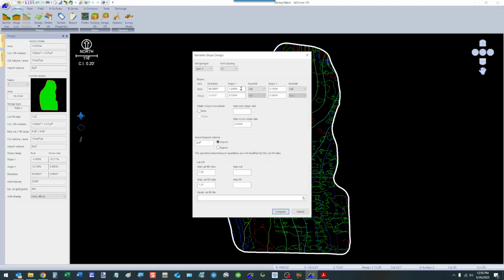So in this case, it'll fall no more than 1 foot fall per 100 feet. It will fall at least 1/10 down the middle, and it can go up to 5/10 fall side to side, north or south. So we don't care because we're going to have a row that is going to contain the water. And in my experience, in doing this for years, whatever this slope is right here, I try to keep it somewhere between 3 to 5 times whatever this minimum slope is.